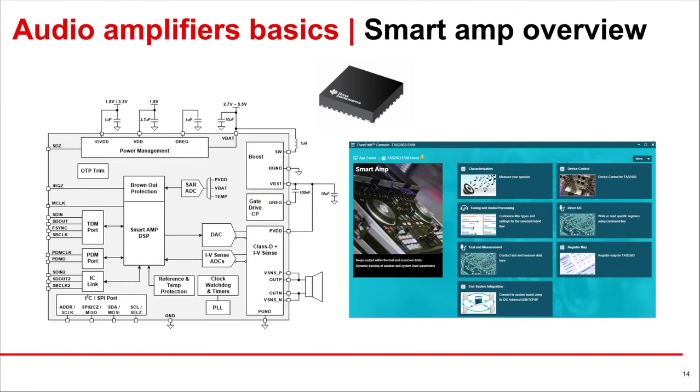And finally, one of the recent innovations in the world of audio is the TI SmartAmp. TI SmartAmps are essentially Class D amplifiers with the addition of a DSP, DAC, and IB sensing. This allows for direct digital input, real-time signal processing, and speaker protection algorithms all to be integrated into one package. This innovation allows designers to safely drive higher volumes, higher bass, and higher quality audio through modern compact speakers, such as those that can be found in cell phones, laptops, and tablets.